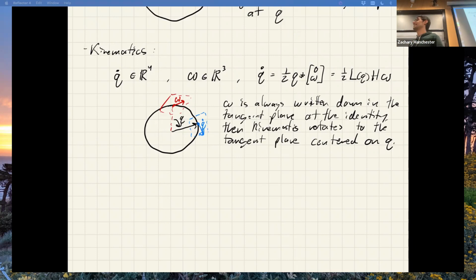Could you talk a little bit more on body frame? Oh yeah. So I have my robot, and it's rotating around. The definition of a rigid body comes down to this: I can take this thing and slap a coordinate frame on it that's attached to the body, but I get to make it up. So now I have this frame attached to my drone, and then I have some world frame that I painted on the walls of the room. So the definition of attitude is the rotation from the body frame to the world frame.